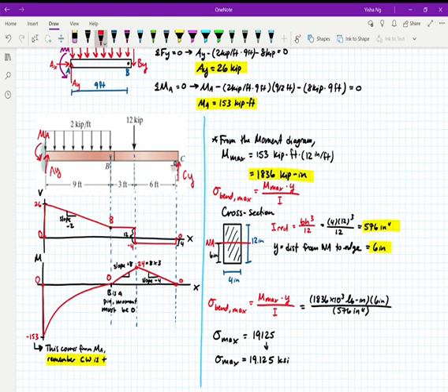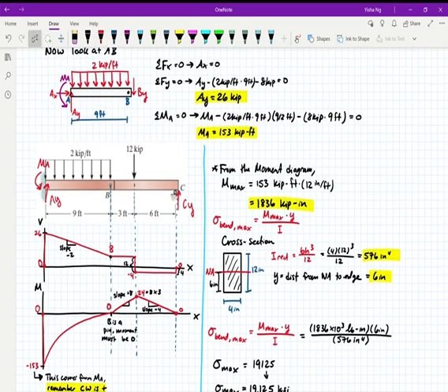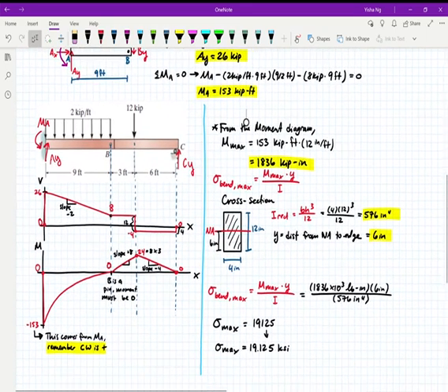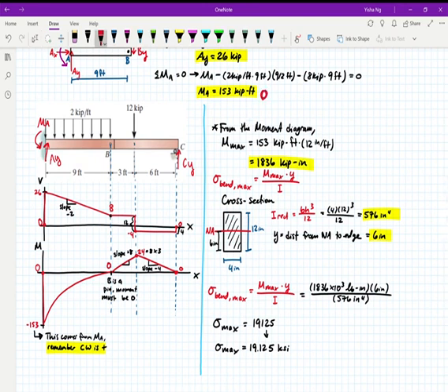Remember what I told you earlier about sign conventions that's really confusing about the graphical method: clockwise is positive and counterclockwise is negative. Because here I assumed that MA was counterclockwise and I found a positive value for it, when I use it here, I know that it's actually negative. That tells me that on my graphical method, my positive value here becomes a negative value here. So that gives me negative 153. So my external moment is going to cause me to jump from 0 to negative 153.